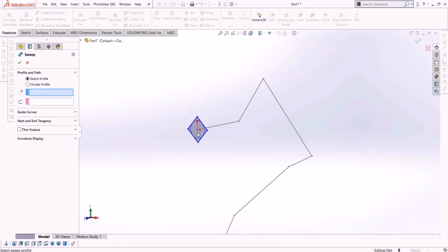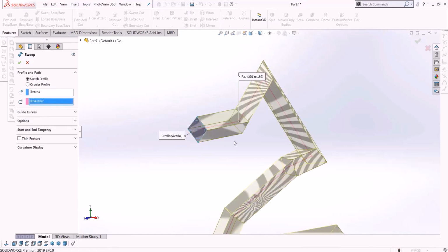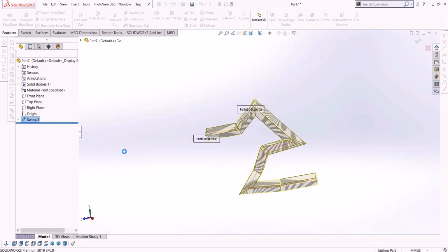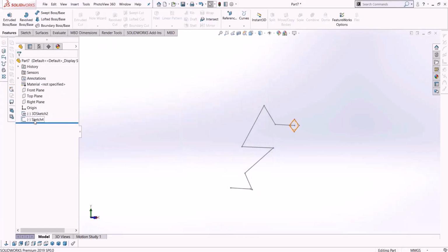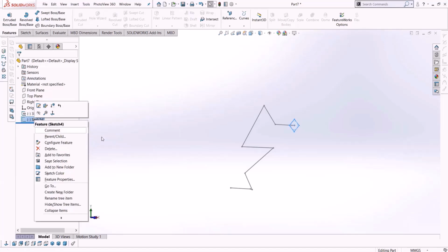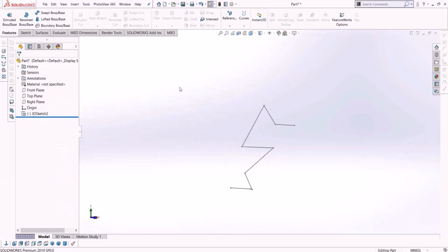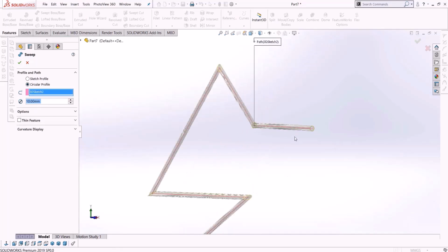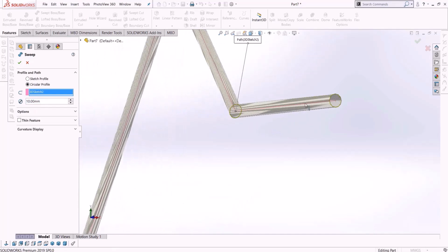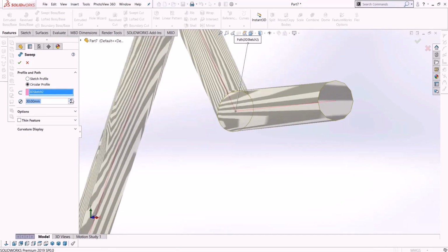This becomes your profile. You might even create a strange shape with spline, and that becomes your profile. That's perfectly fine and has no effect. This will be our path. Okay. Now, I wanted to tell you this. If your profile is circular, you don't need to draw those circles. The sweep option has a feature called Circular Profile that you can select. You see, it won't ask you about the profile anymore. You just tell it, "This is my path," and it will say, "I'll create it in a circular shape." For a circular profile, just tell it how big the radius should be.